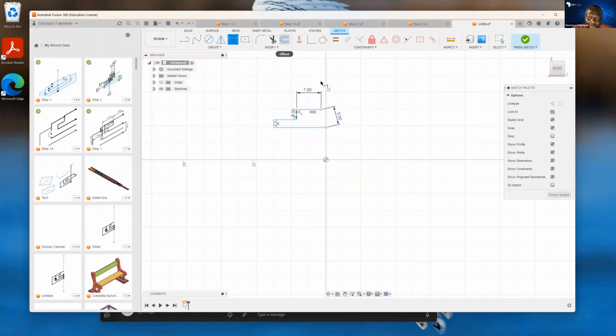So what I'm going to do, I would have to use a constraint because I don't like this bending that I've seen here. So I'm going to choose horizontal, vertical, and I'm going to choose these 2. So I forced those 2 to be on the same vertical line. And I also want them to be on the same vertical line as the fixed origin. So these 3 points, 1, 2, 3, are on the same vertical line. So there is no problem there.